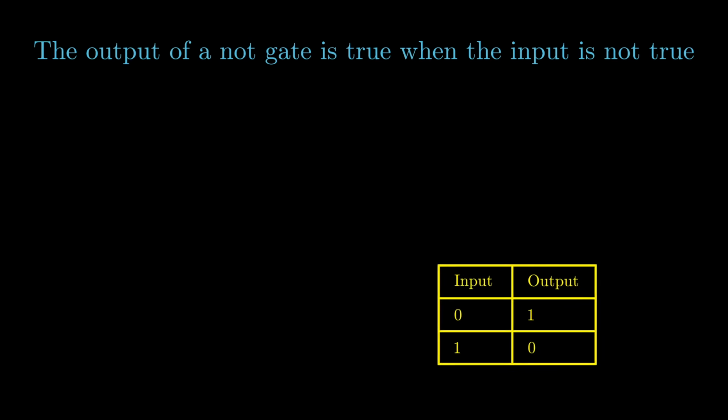Consider this circuit here. For the sake of simplicity, I've omitted the current limiting resistors, but just assume they are there. Notice that when the switch is open, or 0, the output is high, but when we close the switch, the output is low. This gate essentially does the exact opposite of a buffer, so let's give it a similar symbol. Note the little circle on the end. This will be important a little later on.